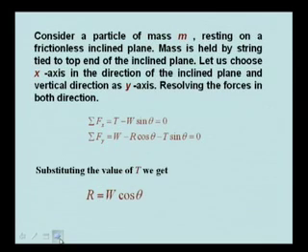If we resolve the forces in both directions, then sigma Fx, resolving the forces in x direction, we get T minus W sin theta is equal to 0. Resolving the forces in y direction, we get W minus R cos theta minus T sin theta is equal to 0.